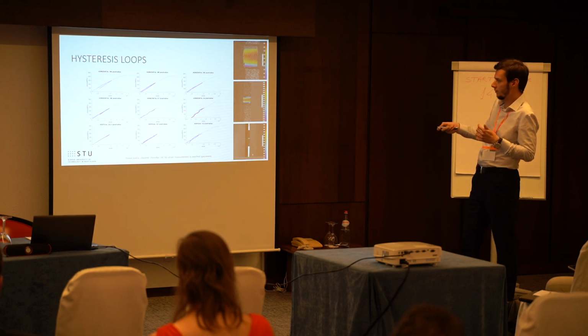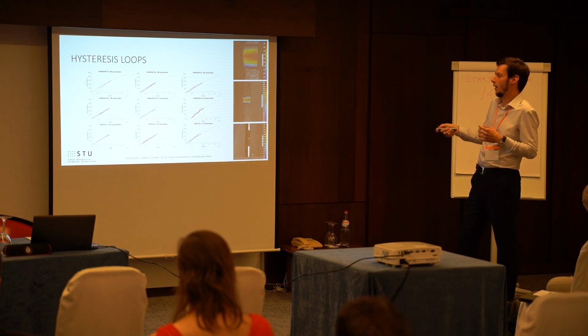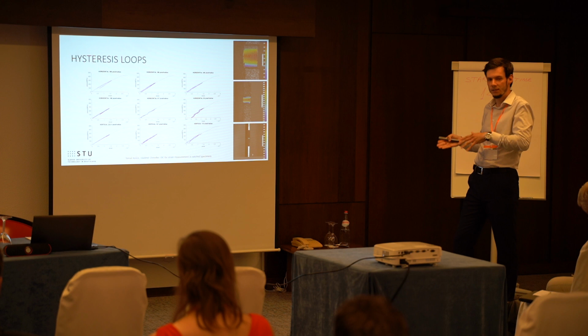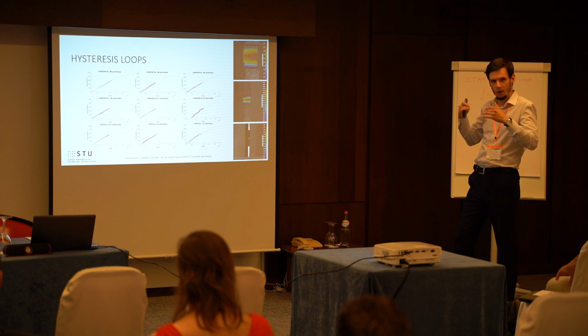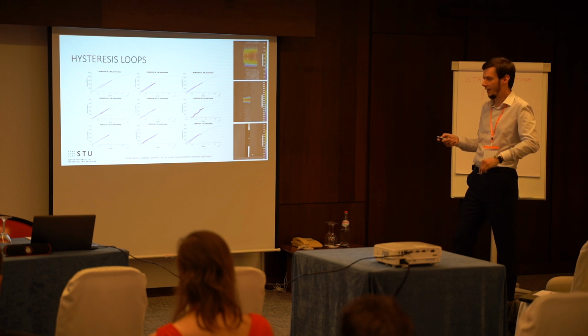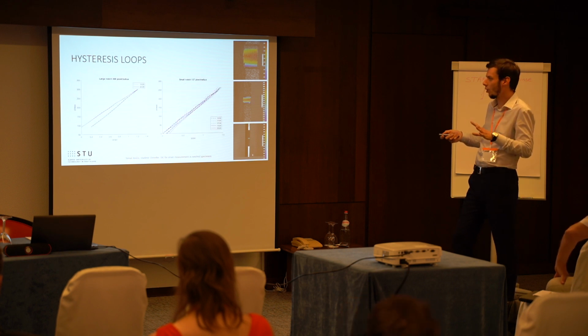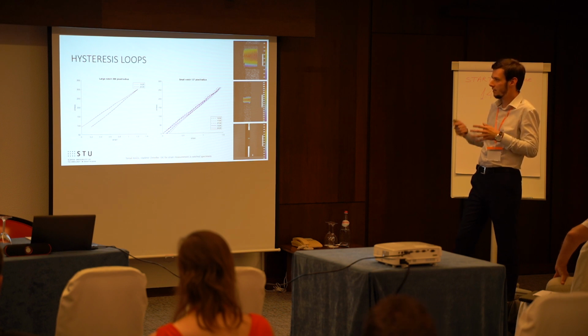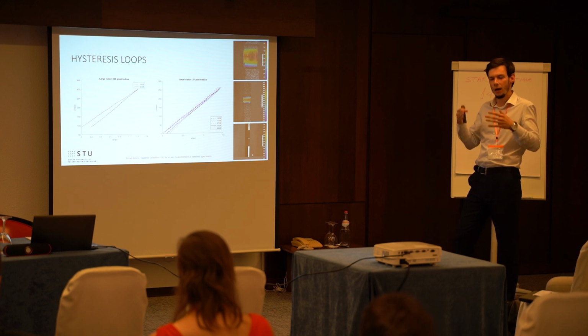Here's the extreme result. The worse we get, it really doesn't look like a hysteresis loop, and in the vertical configuration it's the same. The sensitivity on the filter parameters and the deterioration of the shape of the hysteresis loop are well correlated, and these two effects are correlated with the sensitivity on evaluation parameters like grid size or subset size.